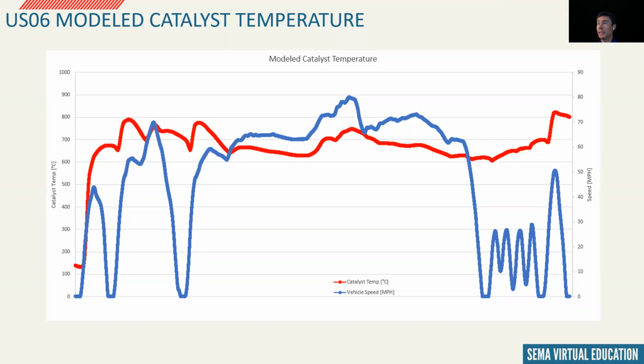Post-catalyst temp data is less intrusive to instrument because we don't need to have an instrumented catalyst by setting a thermocouple into the substrate. We set a thermocouple about 1 to 6 inches back from the end of the catalyst. This is a fair bit easier. With this method, we do need to account for some temperature drop though. 6 inches back from the end of the catalyst will result in a 30 to 40 C drop in temp. This needs to be added to the post-cat temp data.